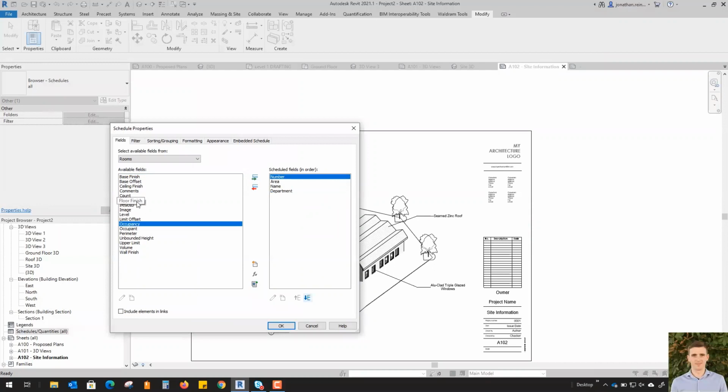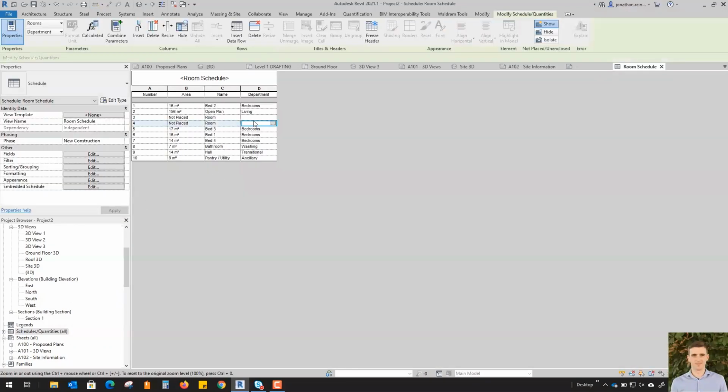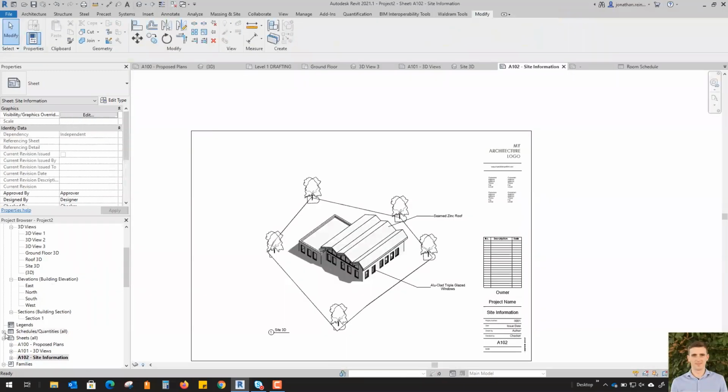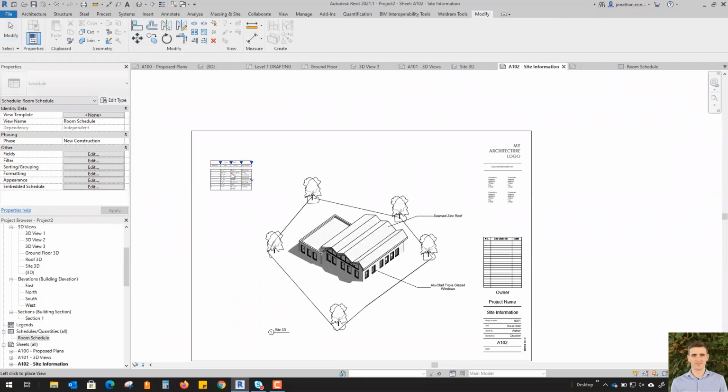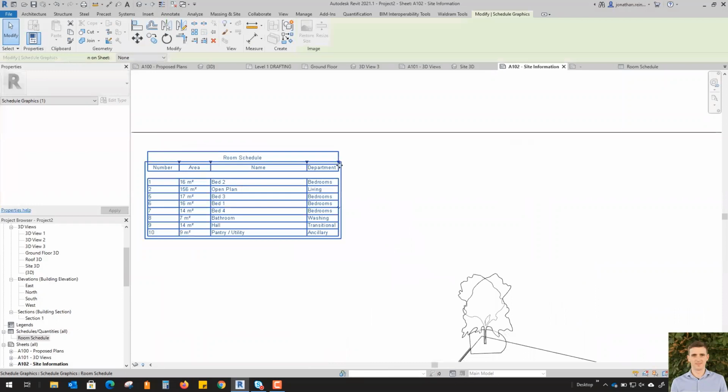Therefore, when you're presenting this to a client, or even if it's being given to a builder for a preliminary cost, they'll have an idea of the floor areas or the size of the actual property that you're going to place. So we just select the different types of parameters that we want to populate into that. And this does actually show up some of the maybe unplaced rooms, and you can just tidy it up and delete those unplaced rooms. They don't exist, so it's okay.